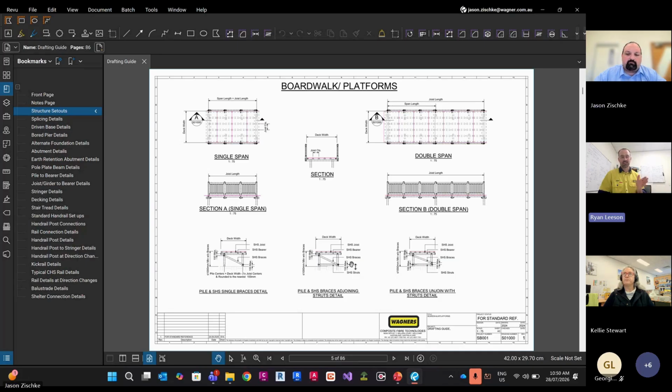In some jobs, we'll detail every single connection if it's a very complex one. If not, we'll just detail a few of them, and then in a schedule at the front of the drawings, we'll just count out the number of those connection types. There's no need to model things for days if it's just a repeat of the prior one. And then our guys typically will just do a manual takeoff with a highlighter and verify that you've called out there's 47 A4 connections. We'll just validate, yep, we're comfortable there is 47, and move from there.